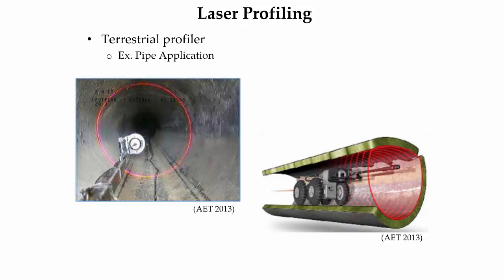The 2 images show a civil infrastructure application of laser range profilers. The rotating laser range profiler is mapping cross-sections of underground pipe debris and deformation information at regular intervals. The remote-controlled truck stops at each interval and the rotating head of the profiler incrementally changes the scan angle to provide the 360-degree cross-sections.